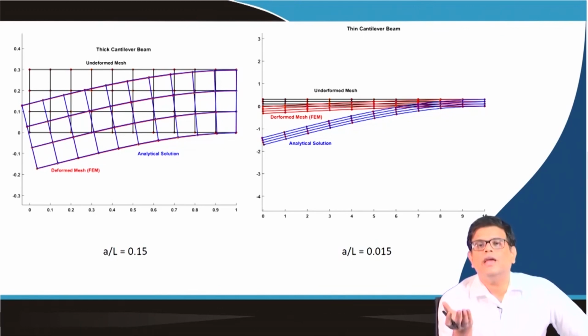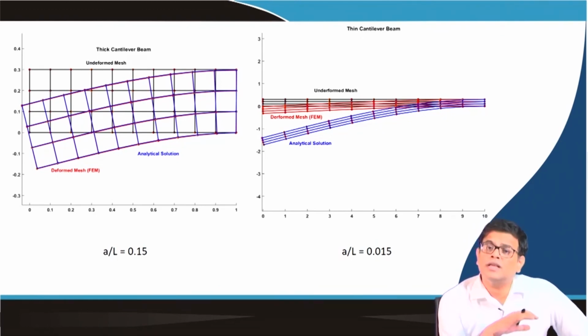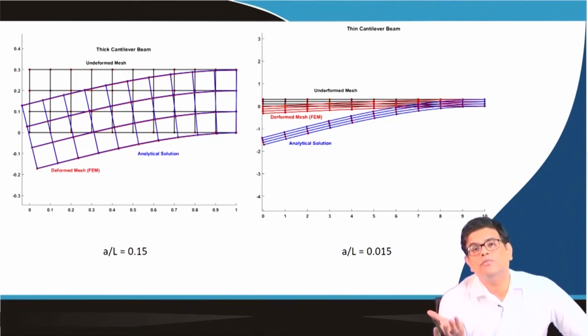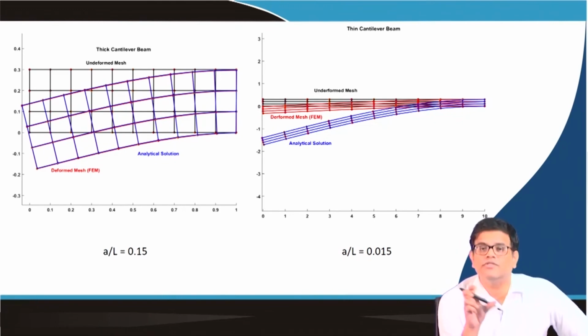In a similar way to what we discussed for the Timoshenko beam, we can also use the reduced integration technique or selective reduced integration technique, where for the shear term in the stiffness matrix we use a 1-point quadrature rule, and for the bending term we use a 2x2 quadrature rule, that is the 4-point.